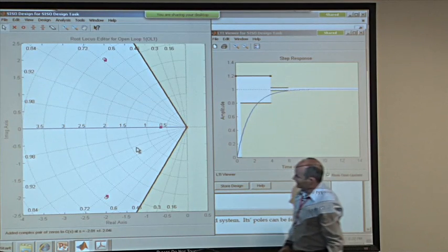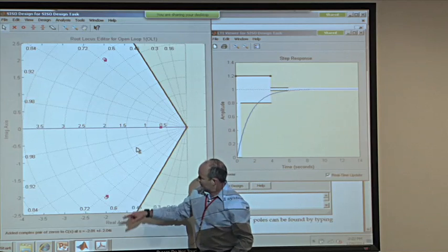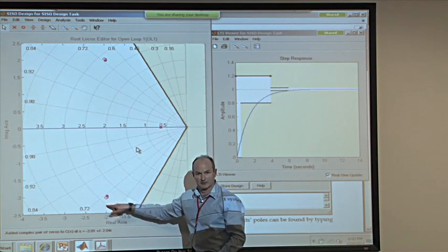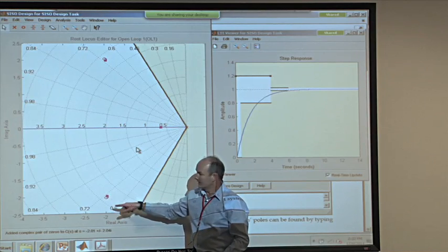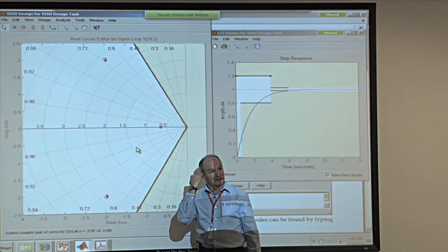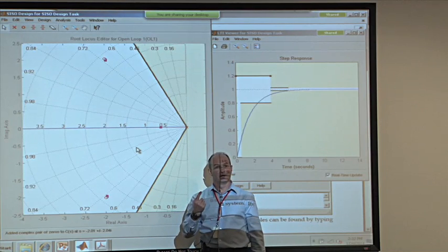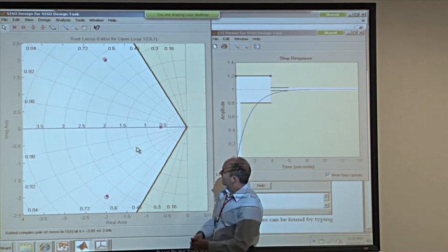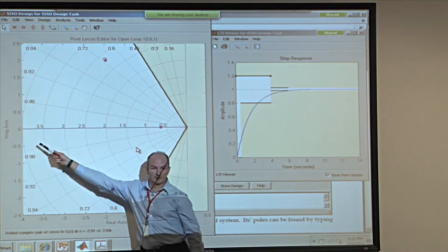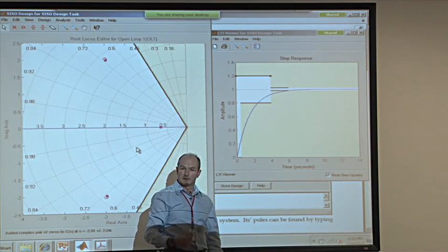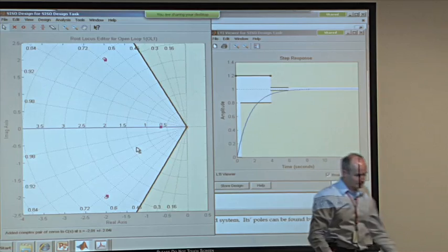And you perhaps can't see, because I've been too accurate, but if I'd missed it by a bigger amount, you'd see a little locus in there. There's a little blue line. That's the effect of cancelling this out. And of course now we've created a system with relative degree 1. 3 poles plus 2 zeros is a relative degree of 1. 1 high gain asymptote, and the response looks exponential. We got rid of the steady state error because there's an integrator in there.